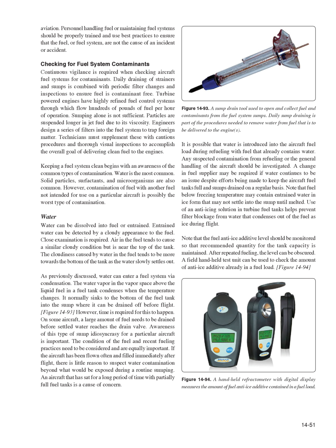An aircraft that has sat for a long period of time with partially full fuel tanks is a cause of concern. Part of the procedures is needed to remove water from fuel that is to be delivered to the engines. It is possible that water is introduced into the aircraft fuel load during refueling with fuel that already contains water. Any suspected contamination from refueling or the general handling of the aircraft should be investigated. A change in fuel supplier may be required if water continues to be an issue despite efforts being made to keep the aircraft fuel tanks full and sumps drained on a regular basis.